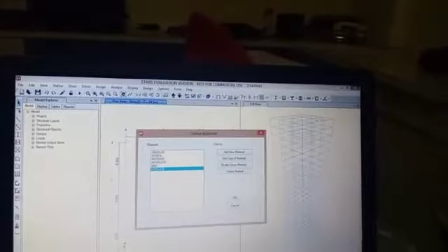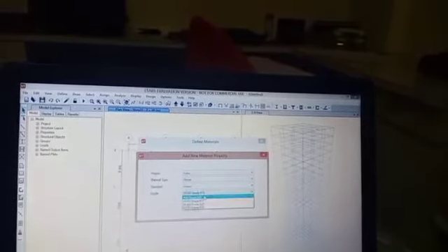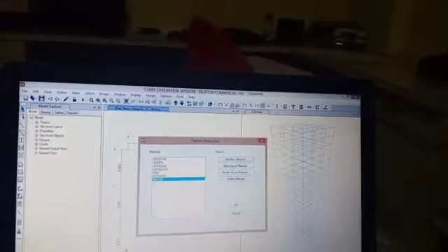Now add new material again, and now material type is rebar and the grade is HYSD grade 415. Click on OK twice. Add new material again, and this time grade as mild grade 250 for the horizontal ties. Now you've added all the required materials.